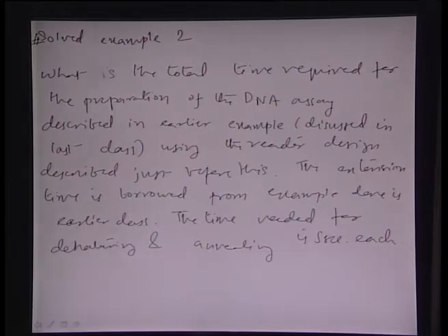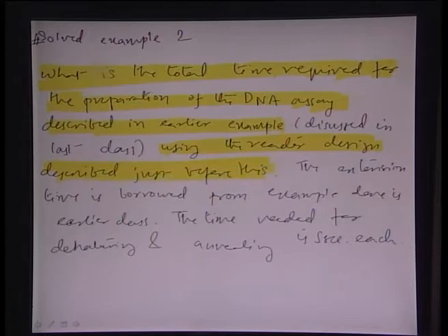In this particular example, we want to find out the total time required for the whole assay to get completed. So we assume the constants from the earlier example, wherein we already found out that the time constant for the process was about 0.28 seconds. Using the reactor design fundamentals, we found out that the total time it would take for the temperature to hit the 90% mark would be about 3 times such time constant, which is 0.84 seconds.